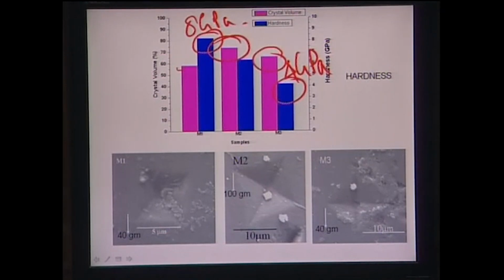To obtain reliable hardness properties, what we have done is that the Vickers indents were also observed in the scanning electron microscope. Then you can calculate the Vickers diagonal with more accuracy and precision, and thereby determine these hardness properties.